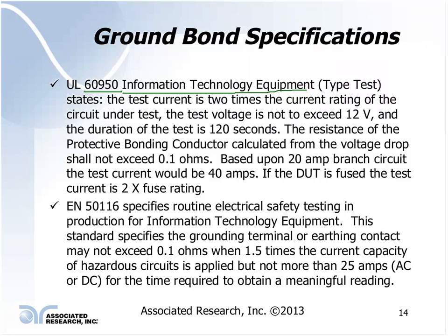I normally recommend a 5-second test just to give you an adequate time to test that circuit. If you do try to do that test, a word of warning: that paper clip will turn red hot. It may melt and drop down onto whatever is underneath of it. If it is a carpet, be prepared. You will set that carpet on fire, speaking from experience.